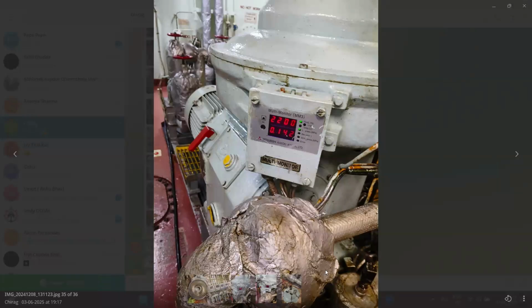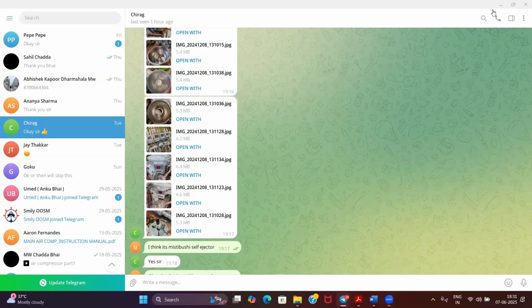There will be a valve at the bottom, right? Which we are adjusting to increase this back pressure. It is right now this much, right? 1.4542. This is my back pressure at the moment. This is the feed. Agreed. So on the return line, on the outlet line of the purifier, one valve is present. You have to throttle that to maintain the back pressure, and you can see the back pressure over here. If somebody has a better diagram, you can show me. I'll tell you. Or wait, I'll be having it here.